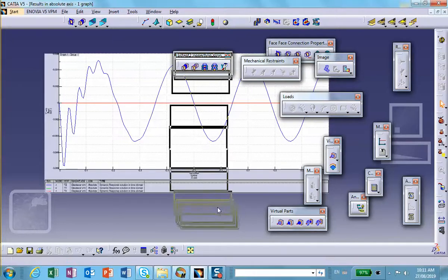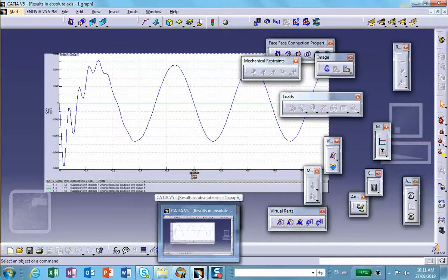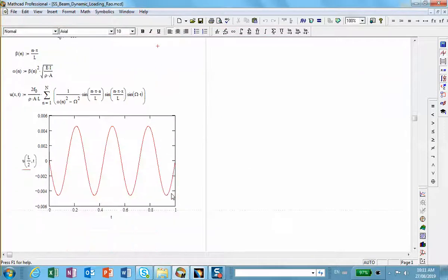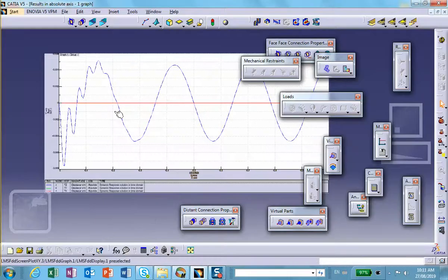Now this is supposed to be this. However, there's some wigglings here which need to be accounted for. And the reason that this is happening, notice that we are solving a transient dynamic problem. And we are saying that suddenly the load is 100 cosine of 7 pi t. That's impossible, because suddenly means t equal to 0, and immediately we have a load of minus 100 pounds applied there. So let me show you a trick to get rid of these wiggles.